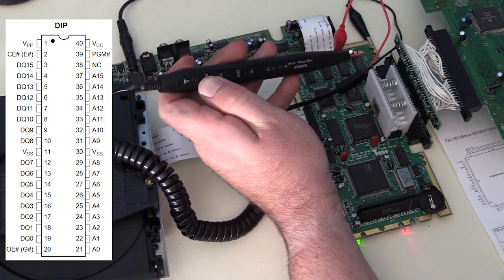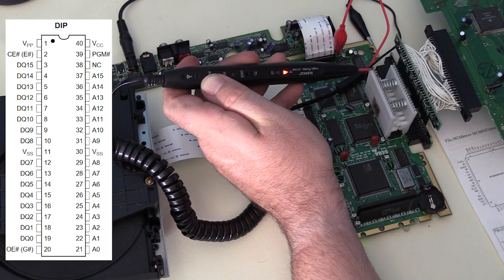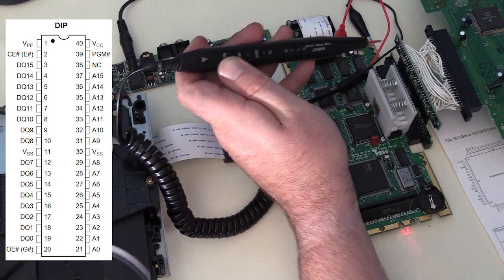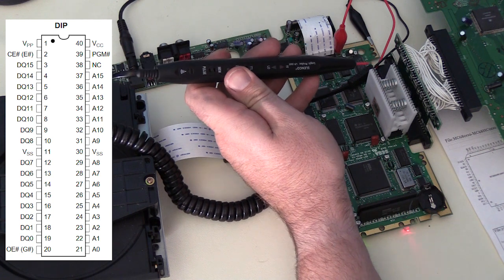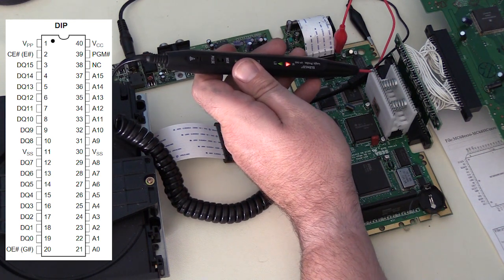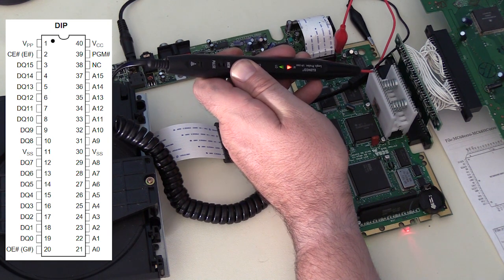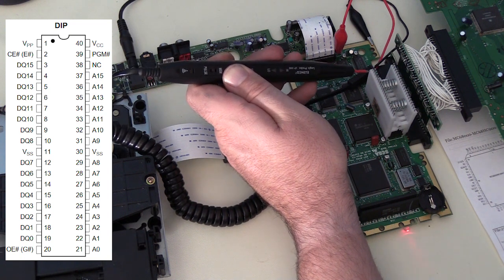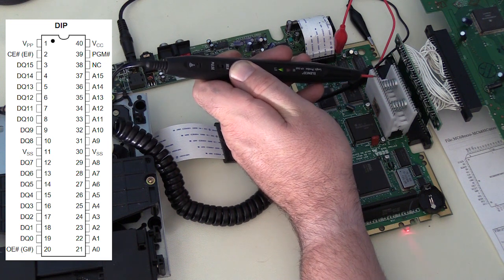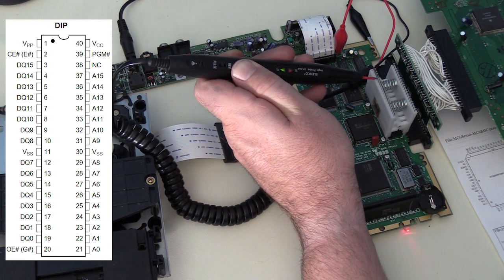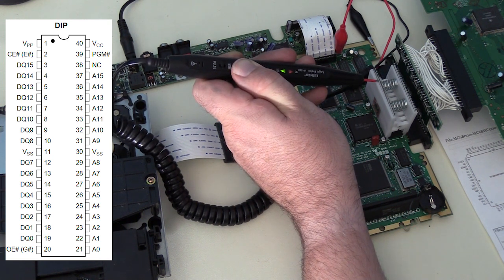Now let's check our pins. Our first pin here is our voltage, and that shows high, which is what we'd expect. Whoops, I just tried to eject it. Let's put it back in. Okay, the next pin should be enable, and that's showing rapid activity because the chip is getting enabled on and off. That's what we would expect. And then next will be our data lines. That's showing activity. That's showing activity too. And we'll just keep going down the line here.